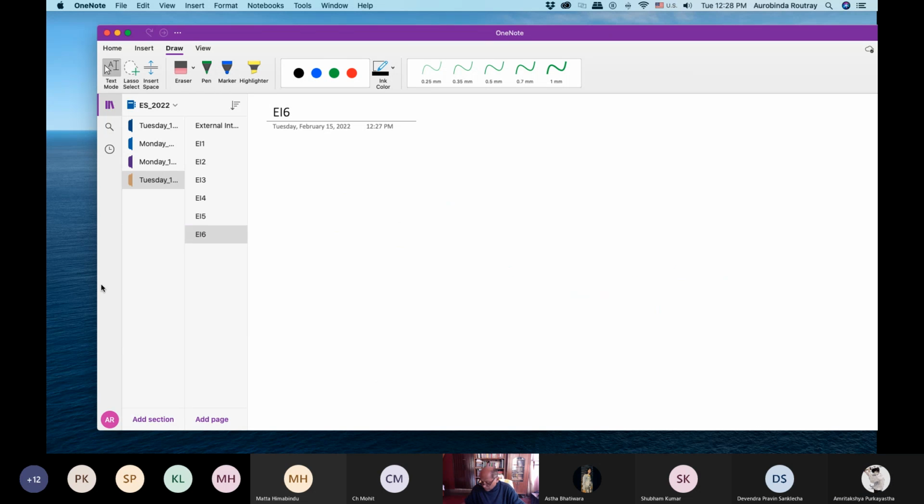So each of the external interrupts is associated with... Forget about the pin change interrupt right now. Let's only focus on the external interrupt. So there is an EICRA. This is a register which is used for control. This is called external interrupt control register A.